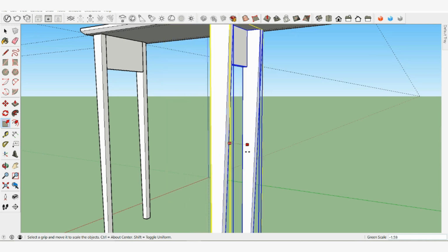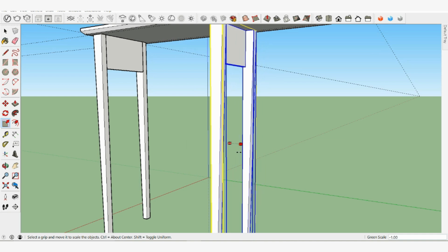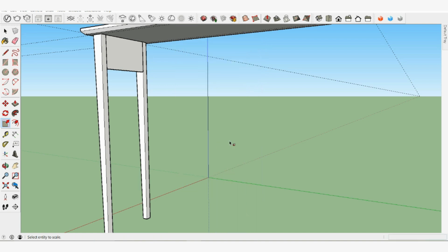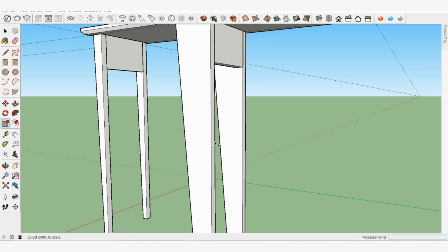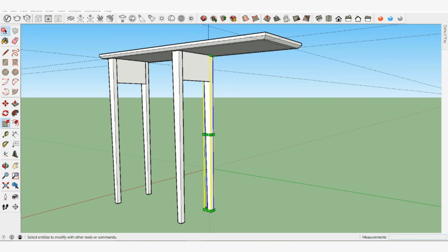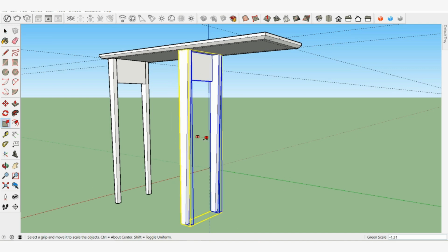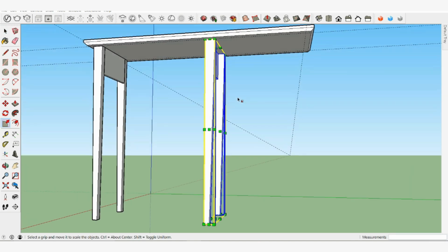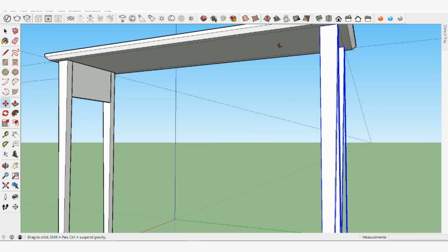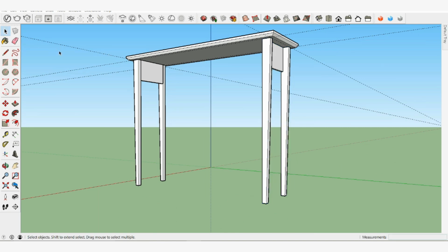To get a perfect mirrored version, watch the measurement sparks. The scale tool works as a percentage. 1 equals 100%, 0.5 is 50% or half the scale, 2 would be then 200% or twice the scale. And if we pull the geometry through itself, it becomes negative. So -1 equals -100% or a perfect mirrored version of our geometry. Undo any scale changes you have created. Select all three parts and scale along this center grip until you see -1, which the tool will also snap to, and click to finish. Now move the assembly into place using the corner of the table and your guidelines for placement.